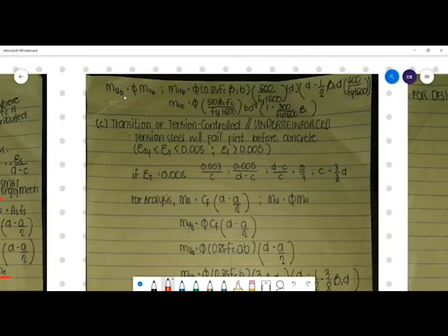we try to derive first Mu in balance condition. So using this one, Mu is equal to phi Mn b. Mu b is equal to phi 0.85 f prime c beta 1 b, times 600 over fy plus 600 b, times d minus a over 2. So one half beta 1 d, 600 over fy plus 600.